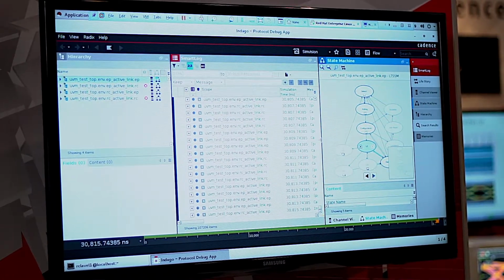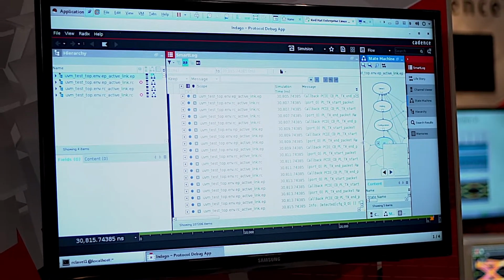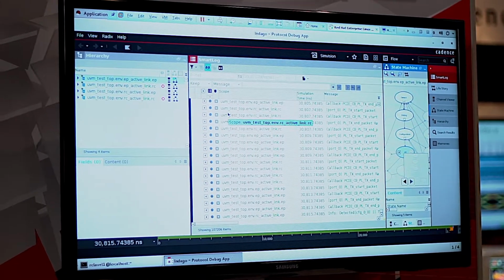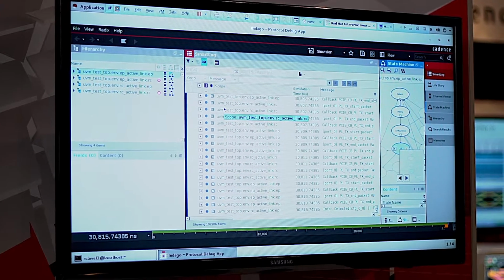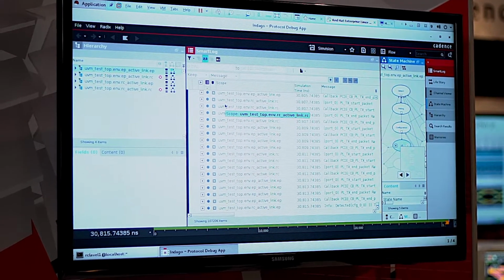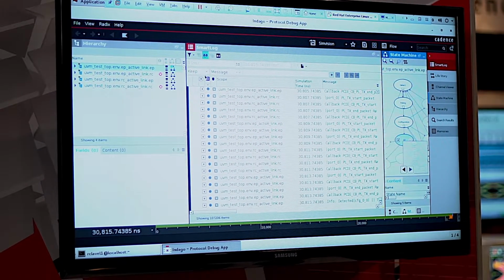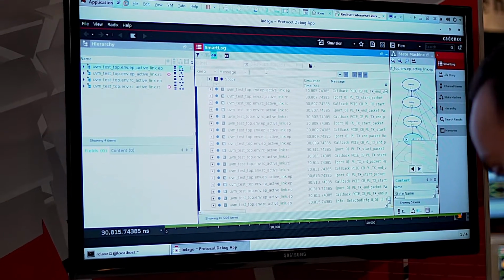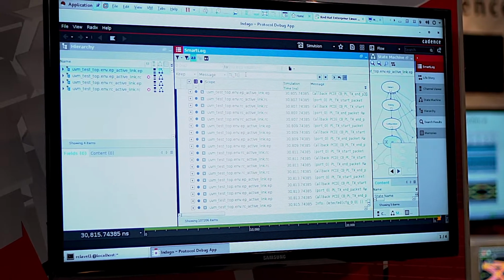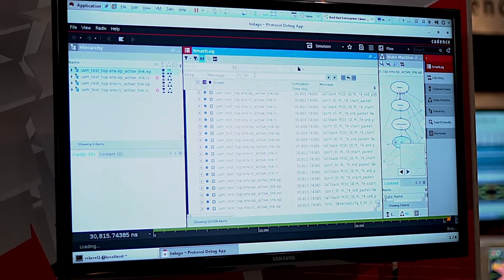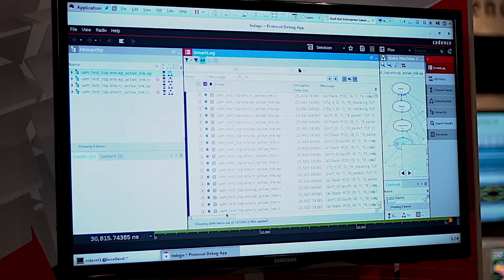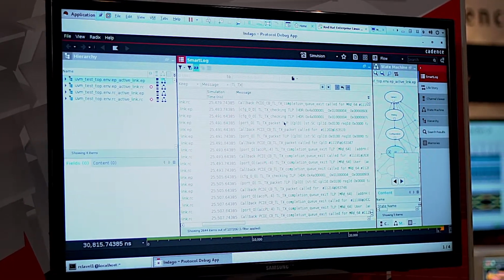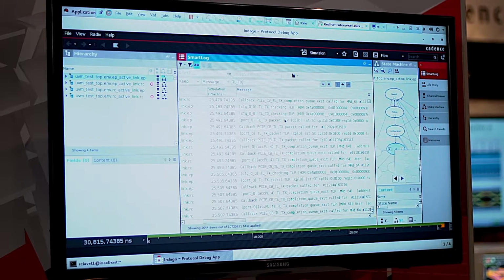So the smart log is a panel showing all the protocol activity. So let's say you were interested in looking at only the TLPs coming out from the transaction layer, then you would add a filter here for keep message, and you would type in TLTX and press enter. This would refresh the screen and you would be looking at only the TL transmitted packets.